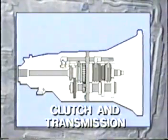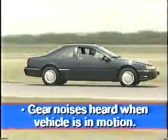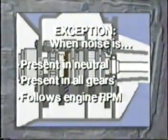Let's take a moment to review the principles of noise diagnosis for typical 5-speed transmissions. Most bearing noises are described as rough or rumbling. Gear noises usually have a higher pitch and are described as howling or whining. Most transmission gear noises are also not present until the vehicle is in motion. The one exception to this is the input and countershaft drive gears.